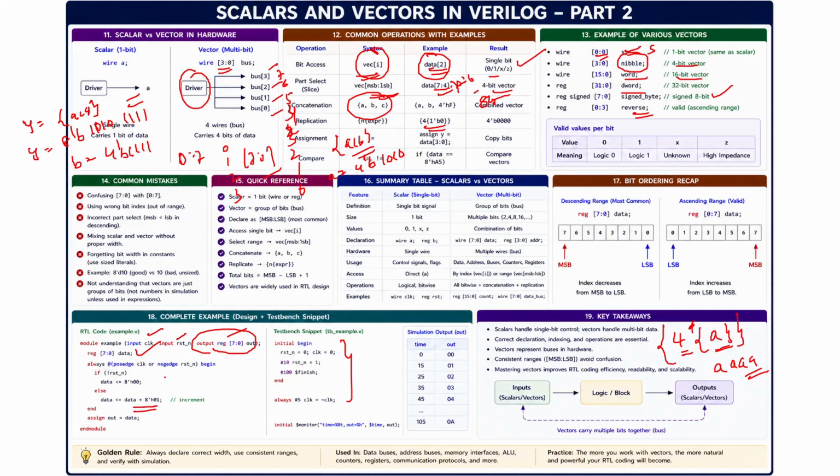So how is it populating the value? During reset, the data is 0. And then during the release of the reset condition, I am incrementing the value here. So data is incrementing, data plus one. That is the registered array we are using there.